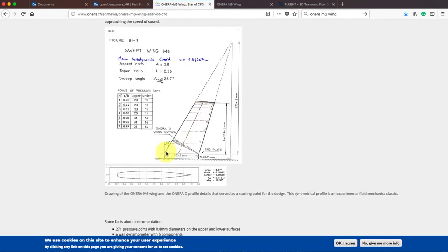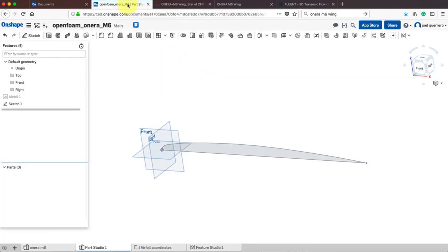What we want to do is that we already have here, remember the airfoil is symmetric, so that's why we have only half the airfoil. You can also put the complete airfoil, it doesn't matter. So we have half the airfoil here, and we need to create it here, but first we need to create these construction lines, construction geometries, okay? We know here that in the leading edge, we have this angle of 30, and we have this distance where these lines intersect. So let's construct these support geometries.